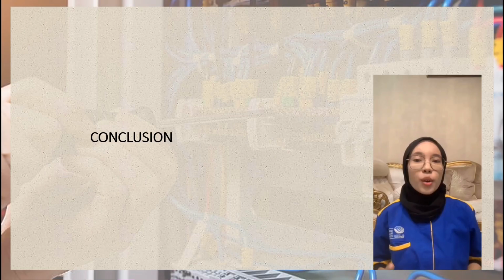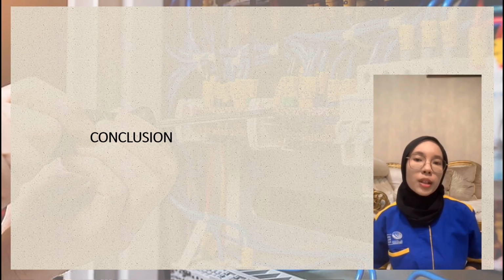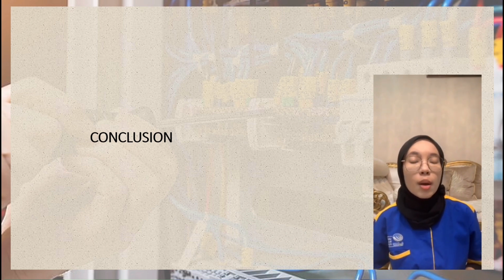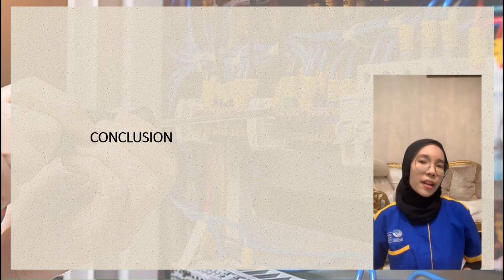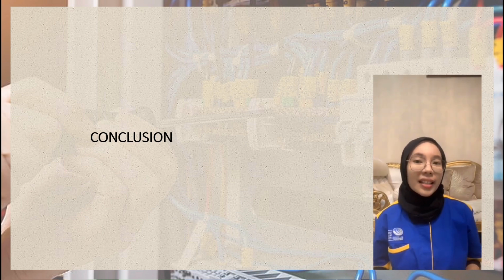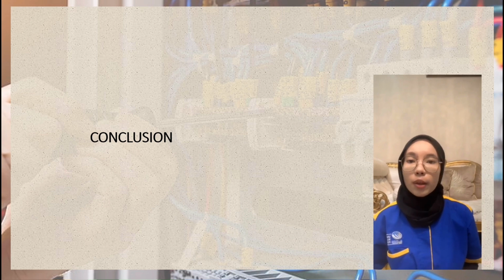Thank you. What I can conclude for assignment 2 is that effective load distribution is crucial for system performance, safety and reliability. Second, it requires thorough planning, proper component sizing and continuous monitoring. Third, carry out careful load calculation to determine the expected power requirement of different electrical loads. Lastly, it is important to find the right place to put the distribution board so that it is easy for maintenance to be done.